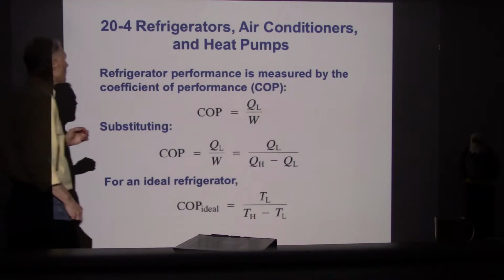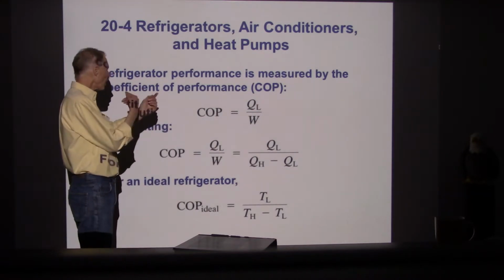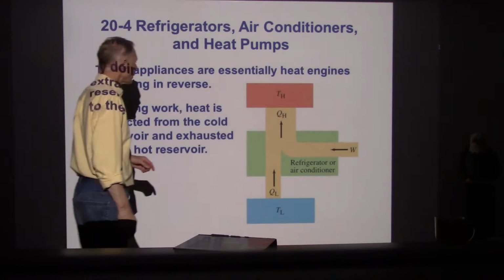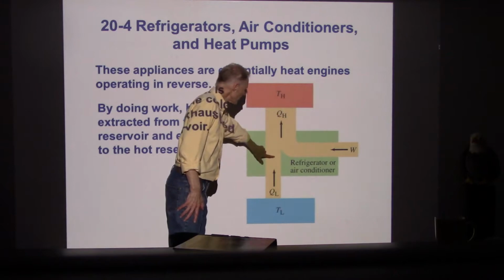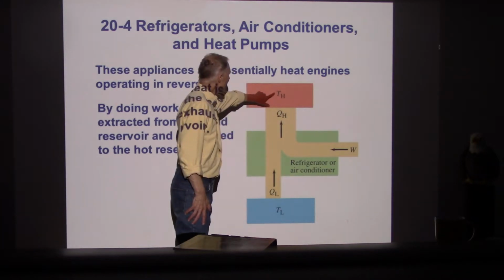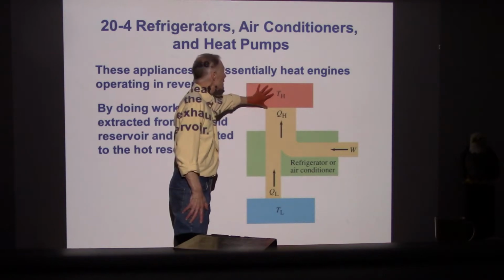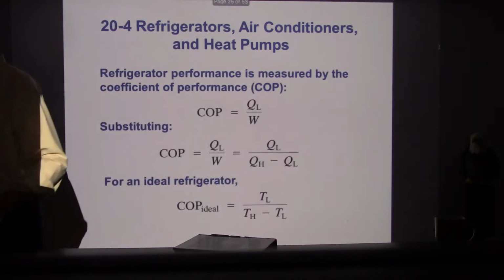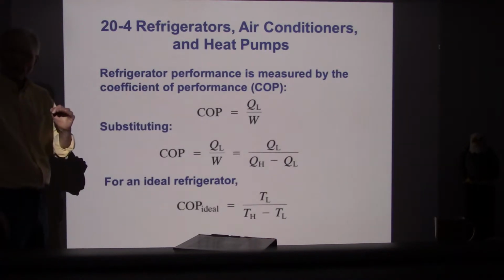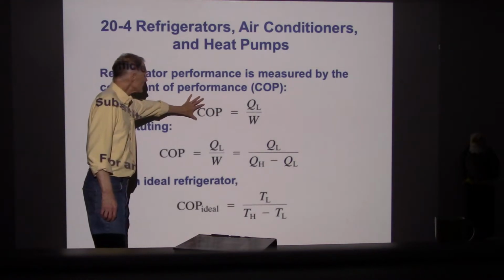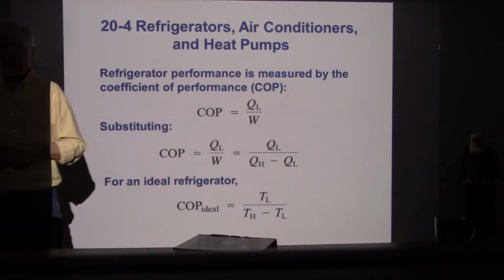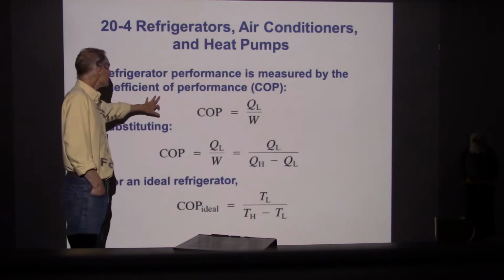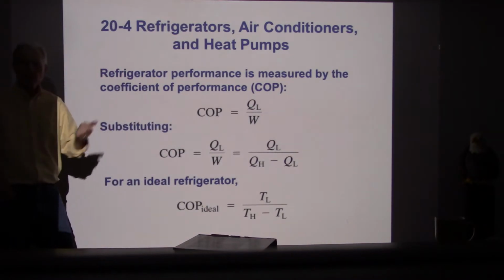All right, for a heat pump, we've got that same diagram, but all the arrows switched directions. So notice what happened: we're drawing thermal energy away from a low temperature region and transferring it to an already high temperature region. Now, that means we can use the same formulas, sort of. We don't define the efficiency of a heat pump as an efficiency, although I'm going to talk about it that way. It's actually strictly supposed to be the coefficient of performance.